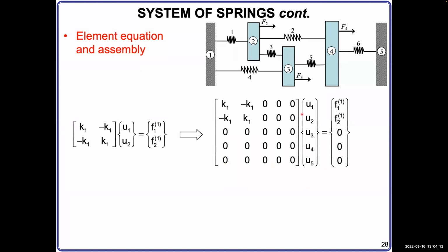And then when we solve, after we assemble them together, we rule out some of the rows and columns based on the reason that the force is unknown and the displacement is known. Then we will have a remaining stiffness matrix. That is called a global stiffness matrix. So these 3 stiffness matrices have different properties. They will come in a sequence.